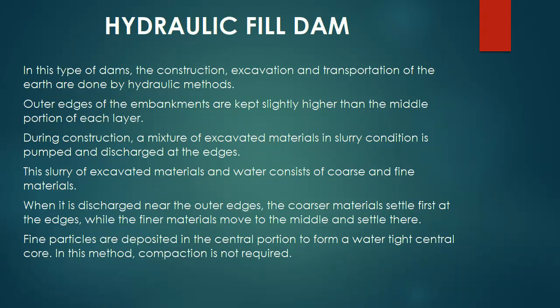When it is discharged near the outer edges, the coarser materials settle first at the edges, while the finer materials move to the middle and settle there. Fine particles are deposited in the central portion to form a watertight central core. In this method, compaction is not required.